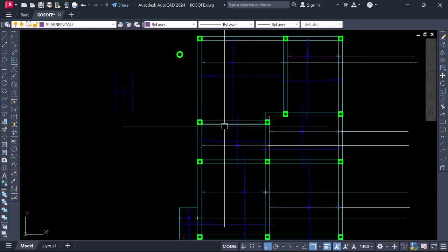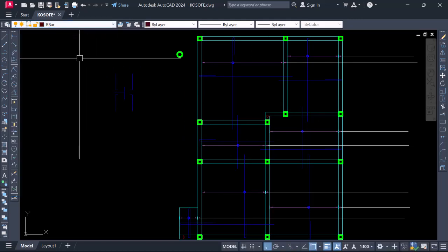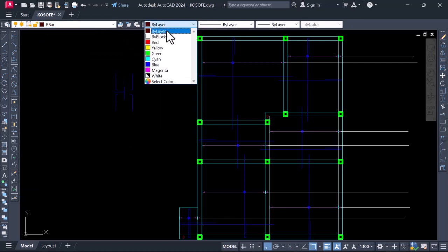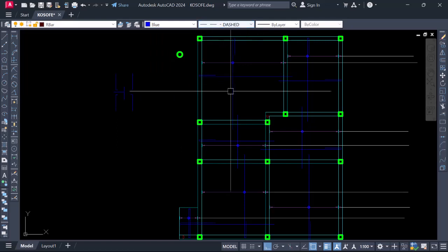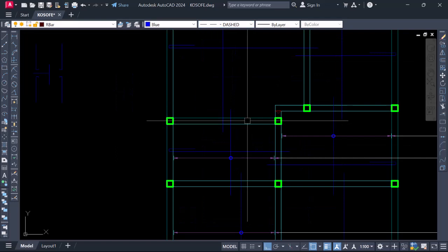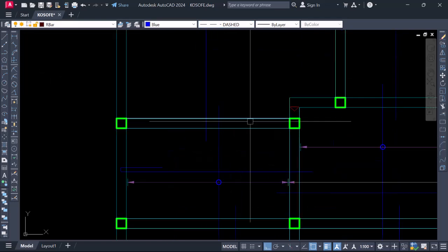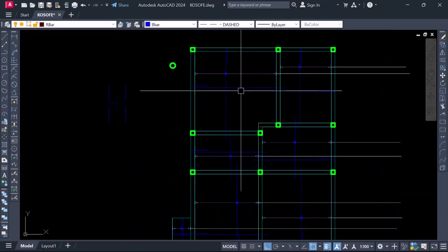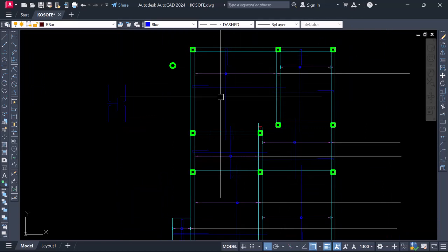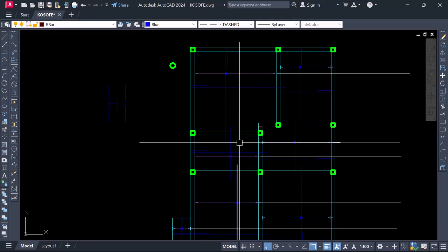All right. So right here, we're going to create another layer for our top reinforcement, and we're still going to get blue. Let's get a dash line to it. So in this regard, we're still going to create our 80 and 80 along this region, since we have a smaller reinforcement. Otherwise, you still consider the 30, the steel theory. You're still going to consider the 30% or the 25% along the span.